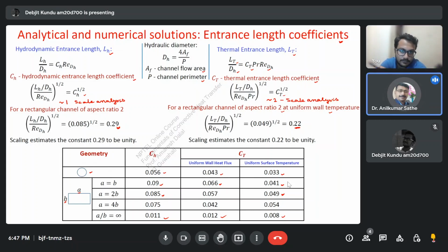What I need to understand here is, for flow to be thermally fully developed, what should be the length of the channel? That means the entrance length is asked, no? Yes, minimum it should be the entrance length. It could be more than that. From the entry of the channel up until the entrance length, it would be a developing flow. After the entrance length, it would become fully developed. So the expected thing is the minimum length of the channel.